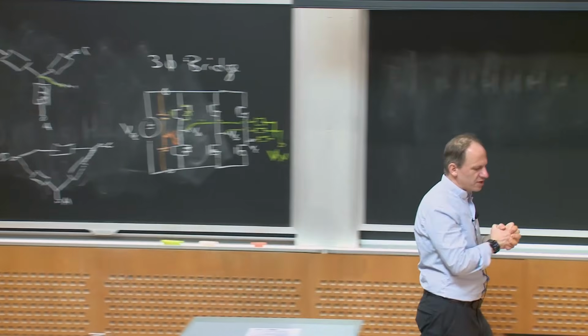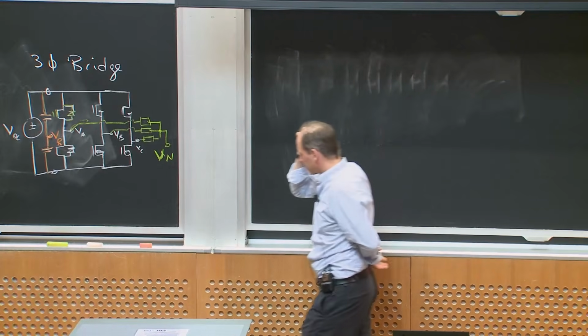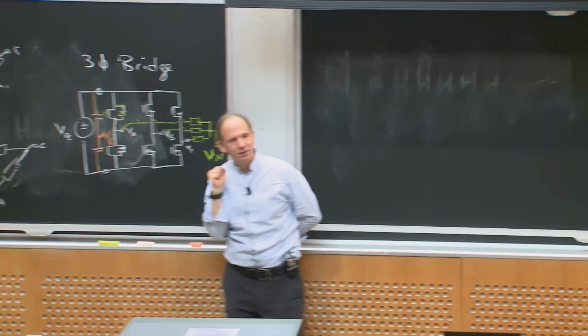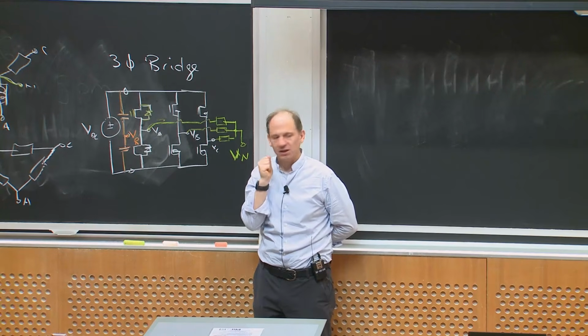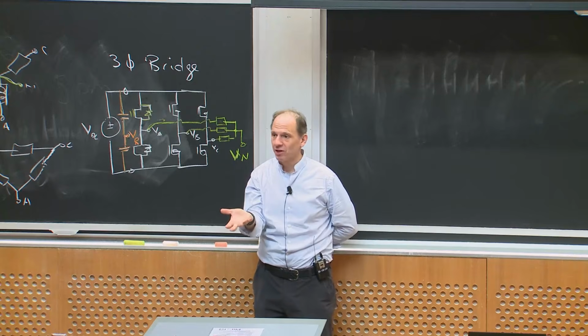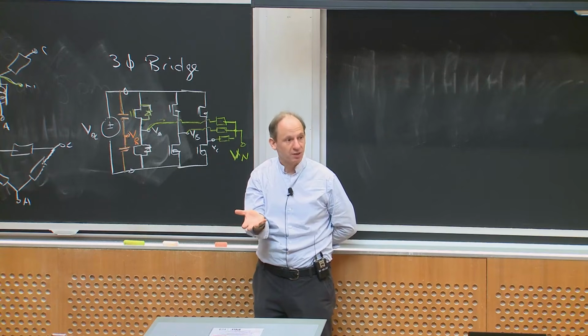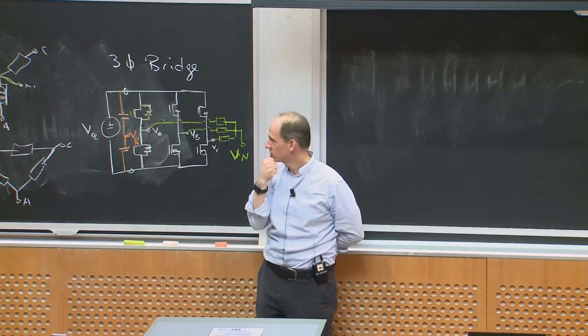So let's think about what we can do with this. And keep in mind, we said one of the big advantages of having three-phase is that we get natural cancellation of all the triple-N harmonics, right? And we're going to see that with this inverter structure.